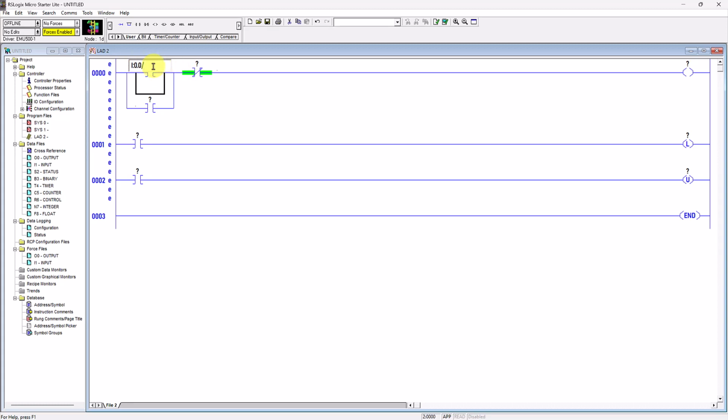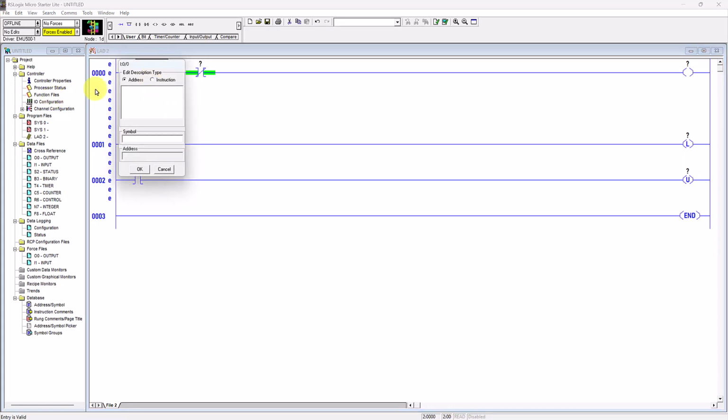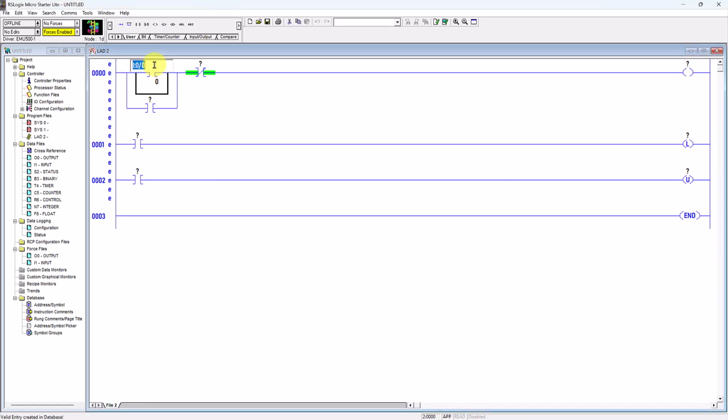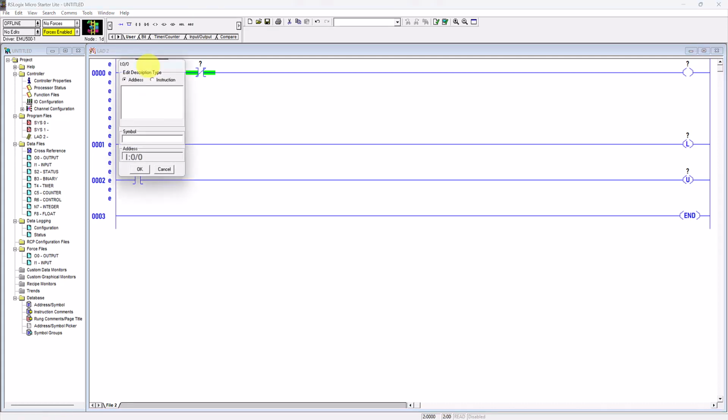Bit means terminal point. Here, let's say I use a bit, maybe bit 0. Okay, then you enter. Then you can write any description that you want. All right, or you also can write in such a way. Okay, digital input column slot 0, instead of writing dot followed by word 0, you can straight away slash 0 and enter. Okay, you can put in any description, let's say switch 0.